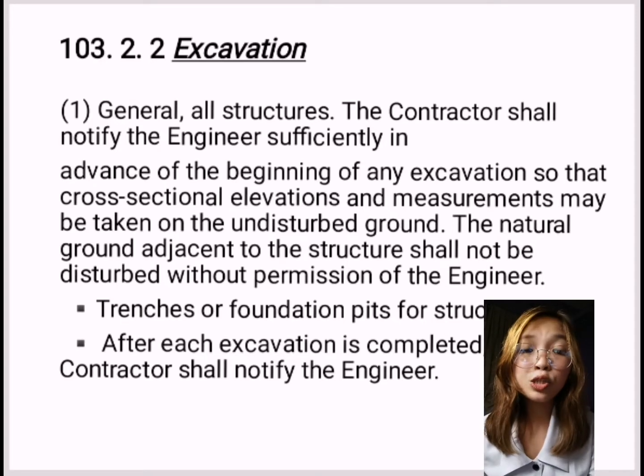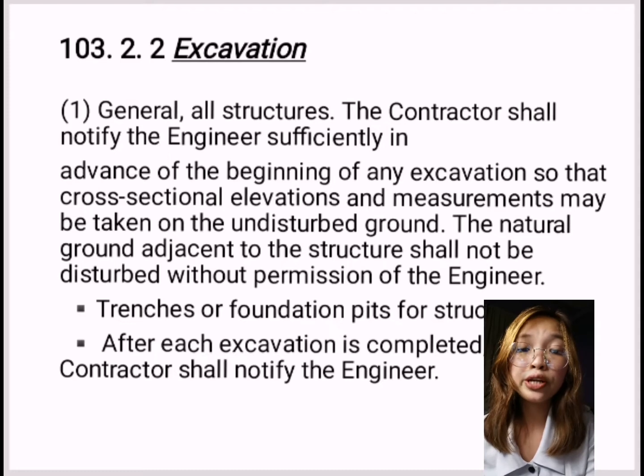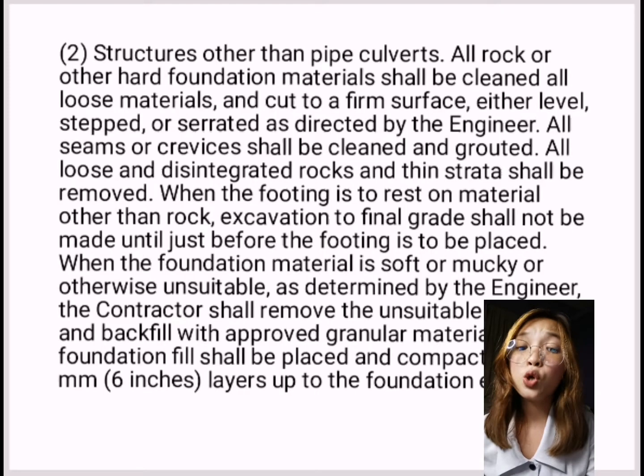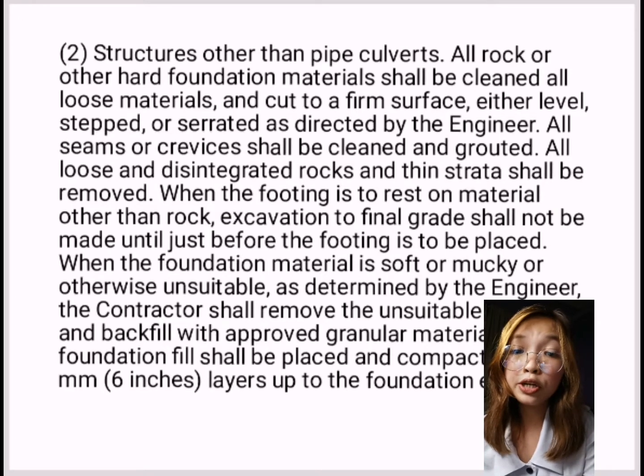So next, let's proceed to the structures other than pipe culverts. So all rock or other hard foundation materials shall be cleaned of all loose materials and cut to a firm surface, either level, stepped, or serrated as directed by the engineer.